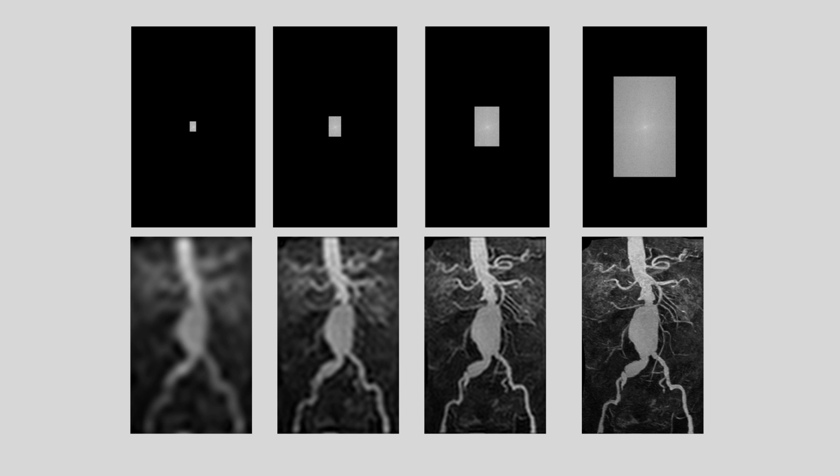And in this case, again I am showing here what I am considering. I am considering the Fourier transformation, and I have to reconstruct the image by using the inverse Fourier transformation. In the first case, you can see only I am considering this portion of the Fourier transform. That means I am only considering the low frequency information, and corresponding to this is my reconstructed image. After this, if you see the second case, I am considering this portion of the Fourier transformation. That means I am increasing the size.